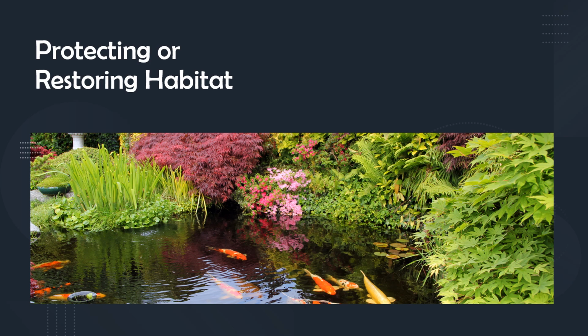Vegetated roof surfaces may be included in the habitat area calculations if the plants are native or adapted and provide habitat. You can get a credit for ensuring that you have sufficient open space. The purpose of the credit is to minimize hardscape, which helps with water infiltration and provides opportunities for residents or employees to connect with nature.